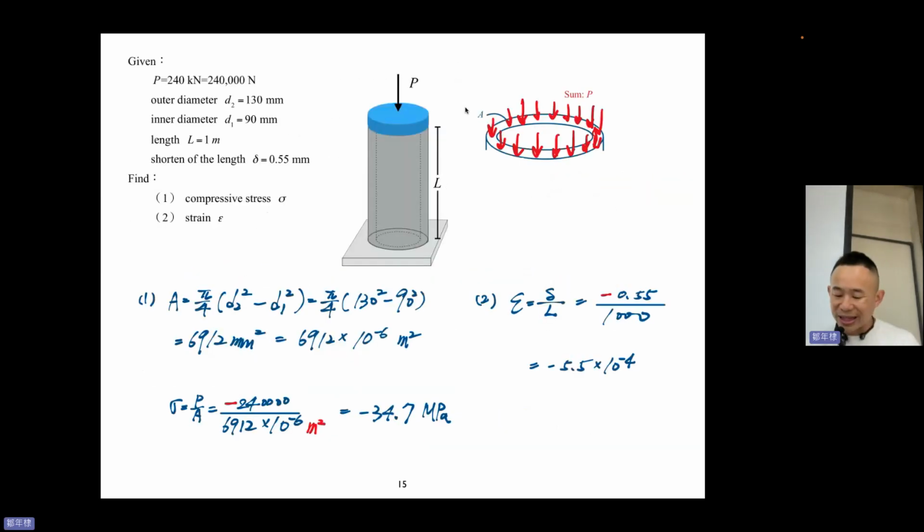And we talked about normal strain, which is just the percentage of elongation. We did some examples, and compressive stress or compressive strain will be negative. The typical value of stress in normal solids should be around MPa or GPa, 10 to the 6 or 10 to the 9 Pa, and the strain should be around 1%, 0.5%, very small.